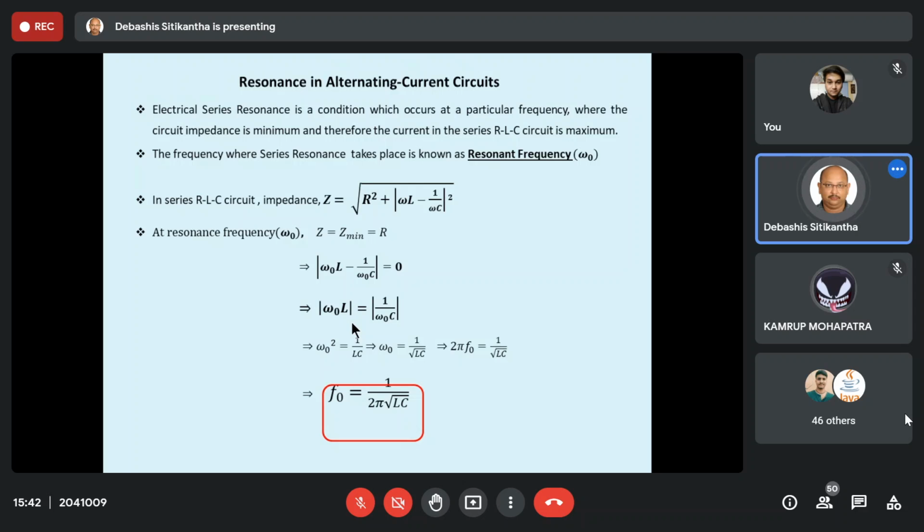For example, the fuel tank lid is undergoing vibration from the engine starting from 0 kilometers per hour till 100, but at 30 kilometers per hour, it is absorbing the maximum vibration energy from the engine. That is why, when something absorbs the maximum energy, it becomes very active and starts oscillating in such a manner that it creates a lot of noise. So this is known as resonance.